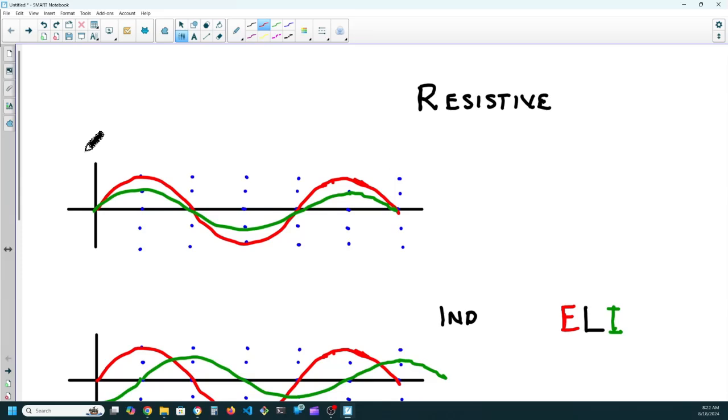If you have an extension cord and you plug it into a light or a drill motor and there's electricity flowing through that extension cord, the wires are made out of copper and they have resistance. The definition of a capacitor is two conductors separated by a dielectric. So the hot and the neutral lying next to each other are two conductors separated by the insulation, the dielectric.